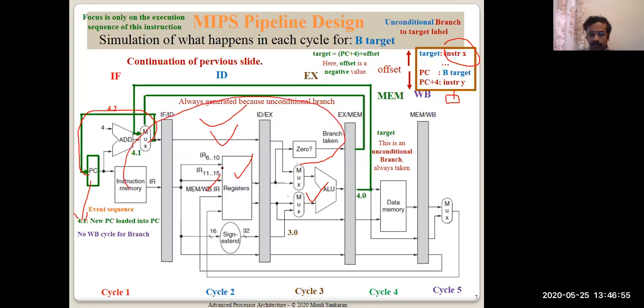But even if it performs, it has not written the value back into the register. So the registers are safe. Even though this instruction came into the pipeline, the state of the CPU has not been changed. These are the things which I want some or many of you to appreciate, because as per the program, we don't want this instruction to cause any disturbance to the program, so it will be taken care of.